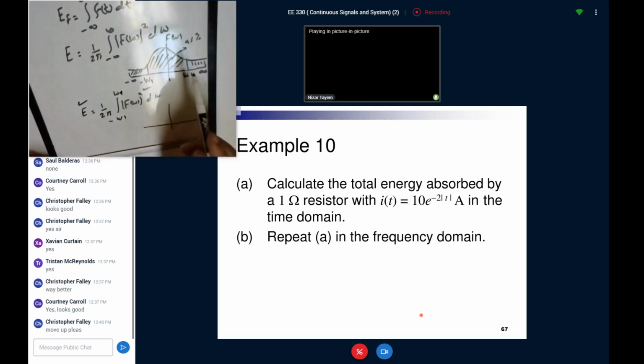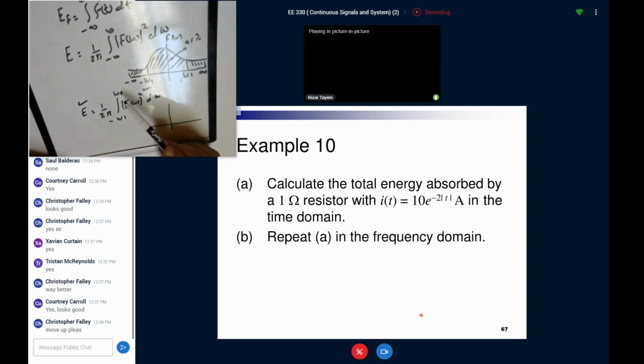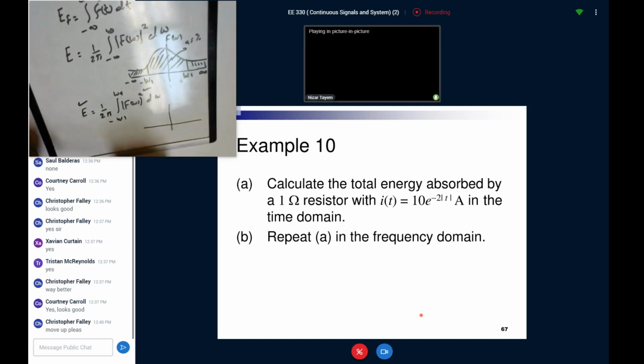But normally, we know that the frequency domain of most signals is an even function. So then we consider only from minus omega 1 to omega 1. Is this clear? Okay, so if I'm understanding this correctly, the minus omega 1 limits are for if it's symmetrical, but as a general case, we would need to do omega 1 and omega 2. That's true, if we're dealing with any signal. But normally, we know from the Fourier transform that the magnitude of F of omega is always an even function. So if you consider an even function signal, then we can go from minus omega 1 to omega 1. For the generalized case, it can be omega 1 to omega 2. Okay, is it clear?